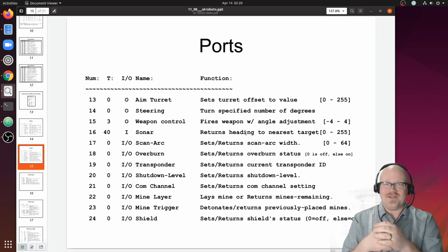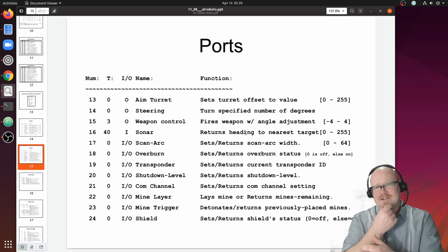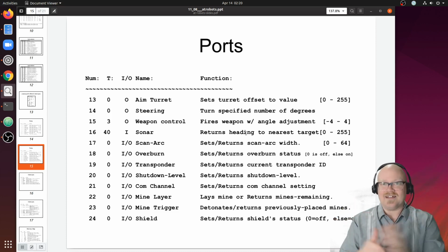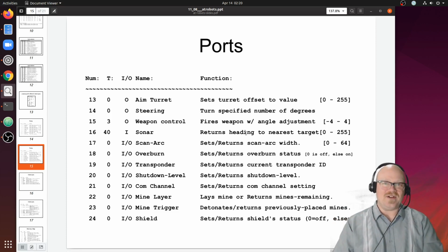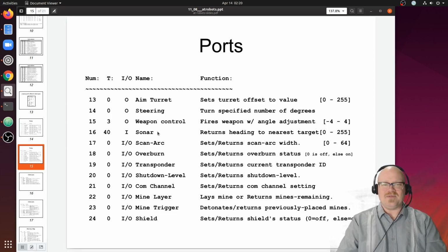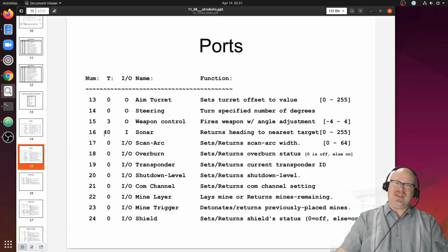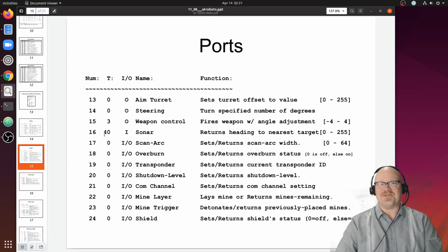But possibly the easiest thing to do is set yourself up a really simple program where you have a robot utilize this particular port and then output the value that it gets from it using the error instruction, which prints it up in your little status area. So you can see what the value is, scratch your chin and say, oh, I understand what that number is now. Right? So we do that a lot in the real world, write very simple programs just to figure out how things actually work. So maybe we'll do that for sonar, but note that the sonar takes 40 cycles. Now that's presumably because of all the fancy trigonometry that must be done to calculate angles or something. But it definitely means that this is an expensive instruction and should be used sparingly.